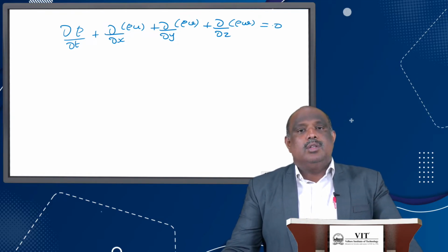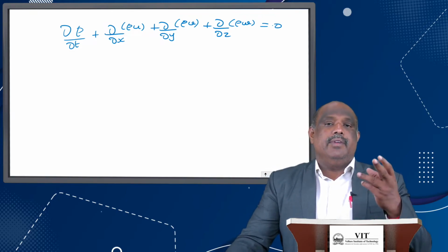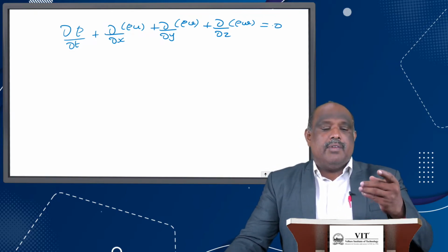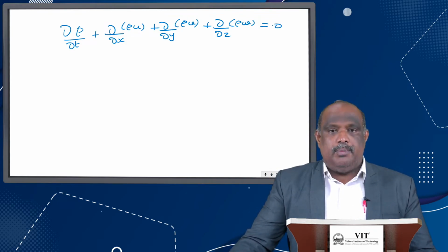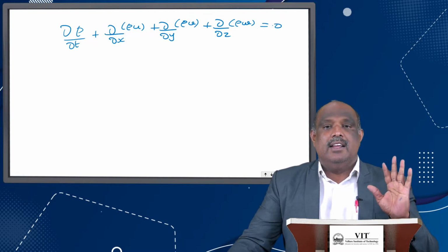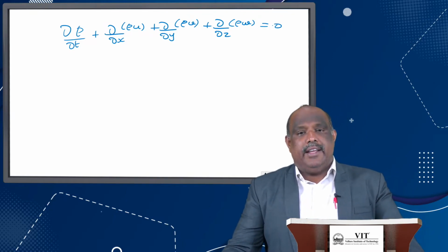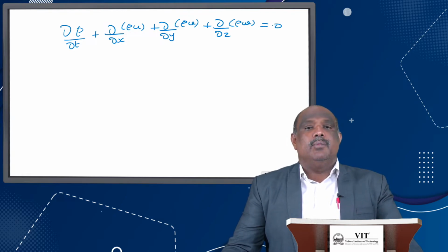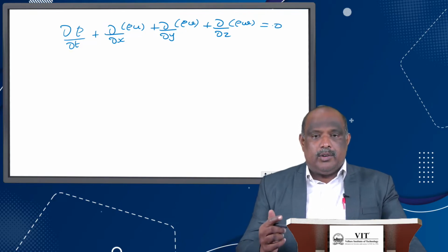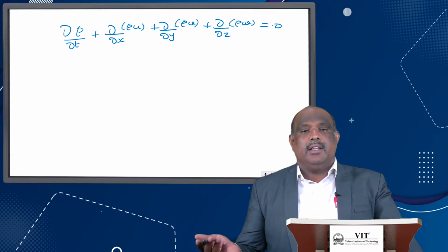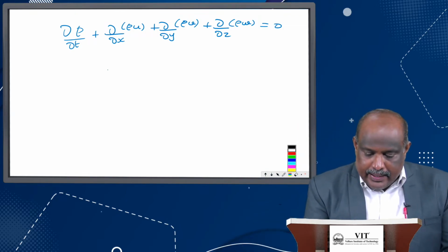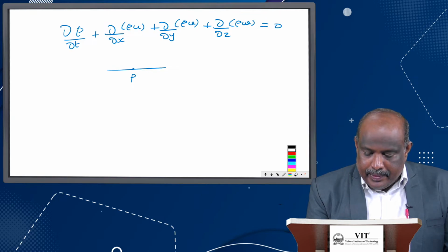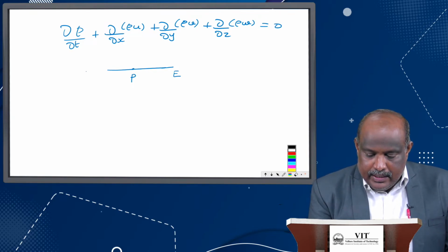Okay, fine. So we have four control volumes: the U control volume, V control volume and W control volume, which are for the velocities, and one more control volume called the main control volume. That main control volume is for the scalar. Since the continuity equation is a scalar equation, we go for the main control volume, or the P control volume. So here the control volume differs from the U control volume. Here the control volume is the main control volume. If you want to draw, this is my P, this is my E, this is my western node.